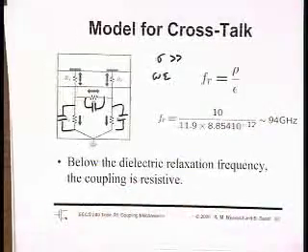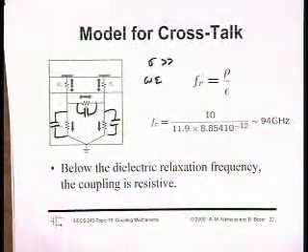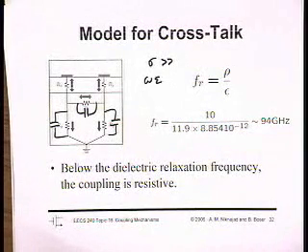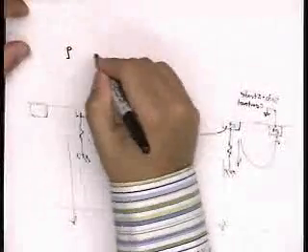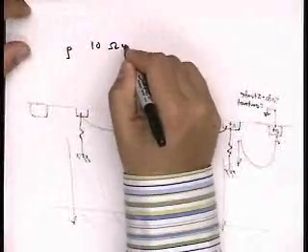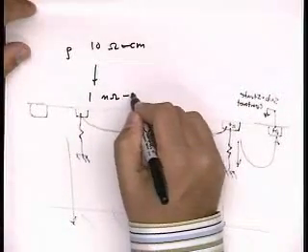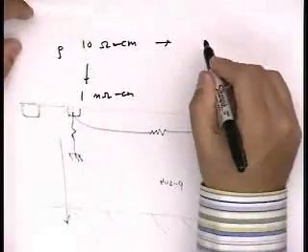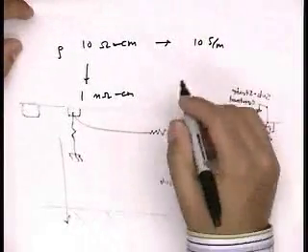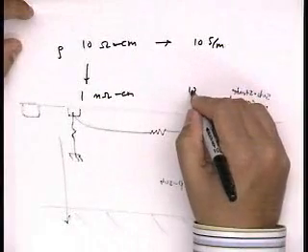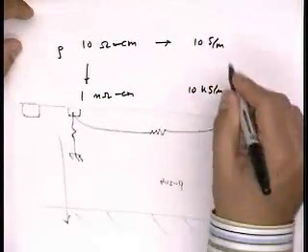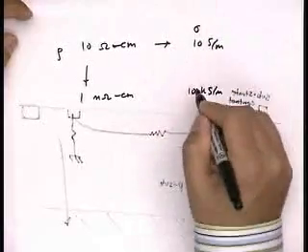Yes? Question, go back to that. What if the rho is much lower, like 10 milliohm, whatever stuff like that? Well, remember, if it's 100 megahertz, then you have to worry about displacement current. But let's look at what we actually have. So I said rho can be on the order of 10 ohm-centimeters to, let's say, a milliohm-centimeter, right? So this works out to be 10 siemens per meter, and this would work out to be 10 kilosiemens per meter, right? So for both of these cases, this is sigma, not rho.